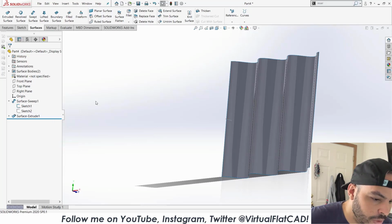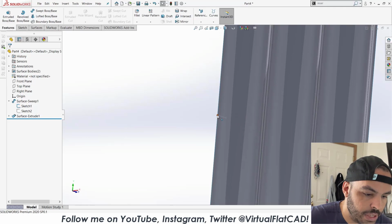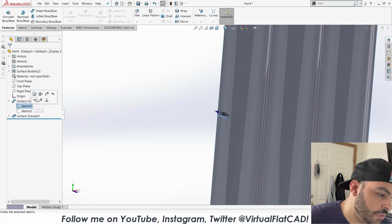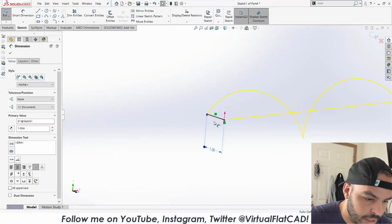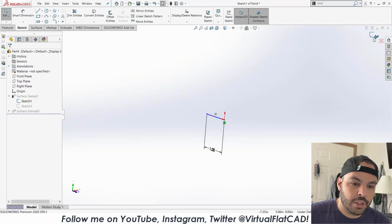So if I show this, make sure Instant 3D is on, and if that's the case, then I can just click. Oh, I have to suppress first. Got a little bit ahead of myself. Put that down there, get that out of the way, and say toggle suppression.